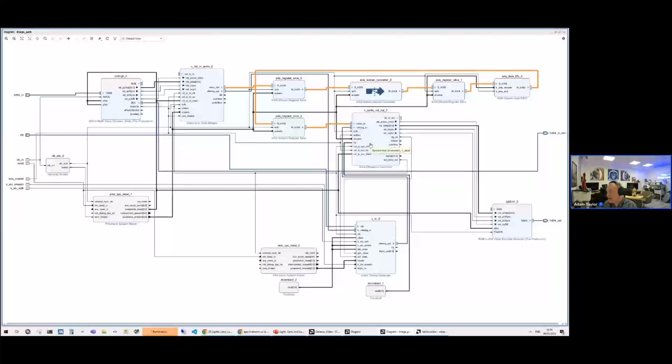Dennis, actually, no, I would recommend using the VDMA. If you're going to put things into memory, there are three IP blocks you need to look at. There's the VDMA, the video write buffer, and the video read buffer, and they'll allow you to do it nice and easily.